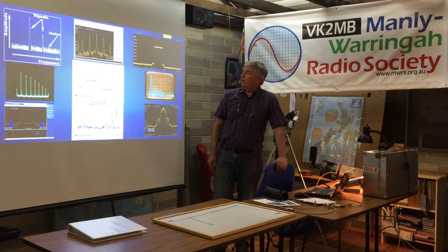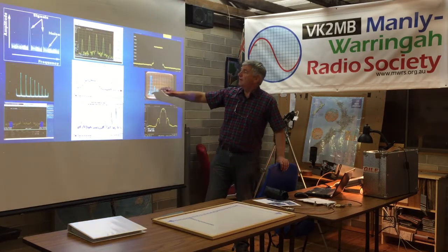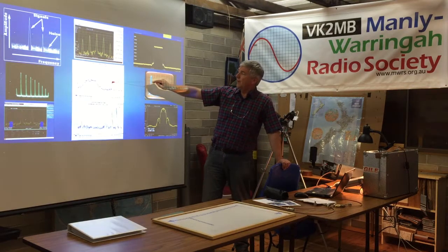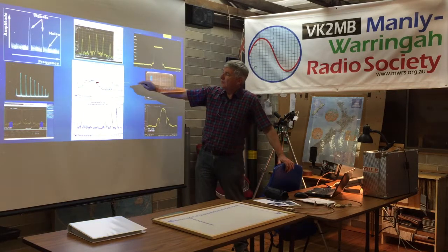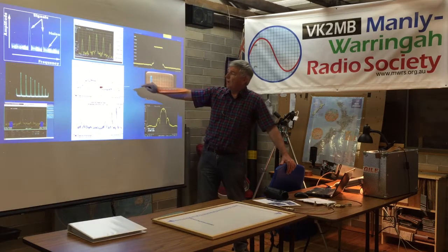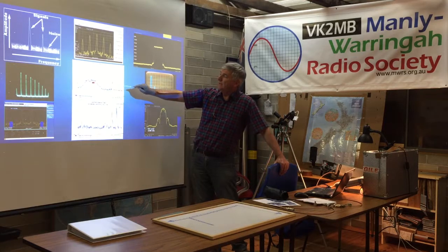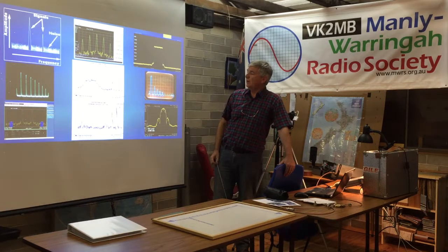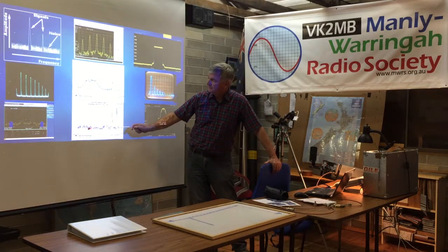He took his spectrum analyzer along, and this is a snap taken inside the shopping centre. We can see some carriers up here, which we can effectively ignore. These are mobile-type carriers, cellular carriers. But what you can see here, centred from about 300 to 500 megs, is a whole lot of wideband noise, and the signals we were trying to look at were residing in here. So this is before, and then Bruce being Bruce, he hunted it down and found out it was being caused by a LED light in a shop. And once the LED light was turned off, bingo, there we go.